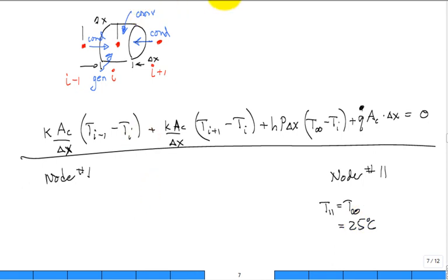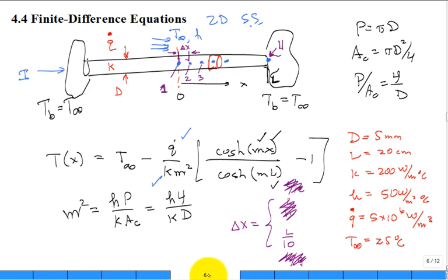So where was node 1, especially in relationship to a control volume associated with node 1, and then here's node 2. So this is node 1, that's node 2. Look again at this mesh here when I cut it. If I say, okay, this is for node 2, I go halfway between 2 and 3, and halfway between 1 and 2 to get that for node 2, right, like that. How much do I have for the volume of node 1? Do I have the same amount as for each of the other nodes? Or do I have half of it? I got half of it.